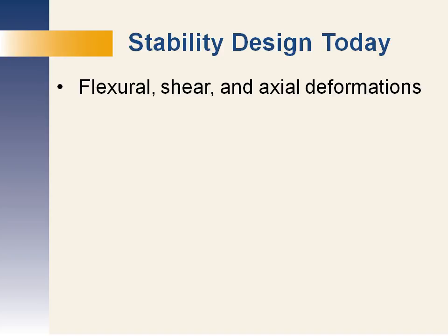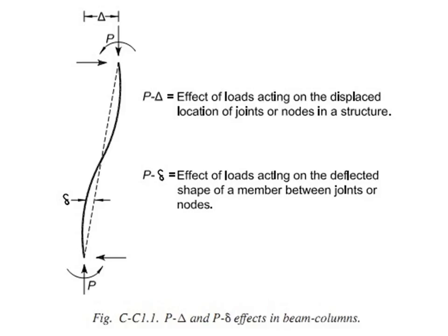These are the results of the first-order displacements of the structure. And then it says we have to consider second-order effects. These are the additional forces and moments that occur due to displacements of the structure that are induced by the loads, like those illustrated here.